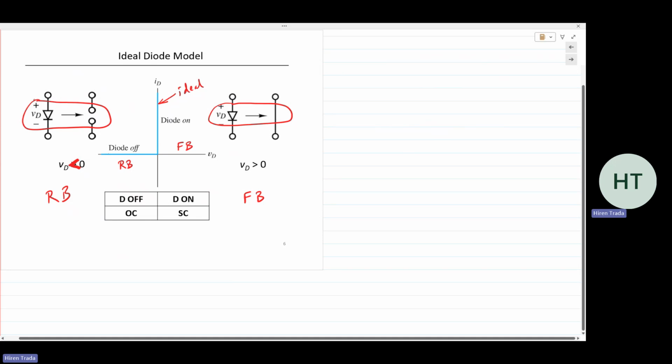In the lab, in lab 1 and even in lab 2, when we use the diodes, if we wish to analyze, we could say that when the voltage goes positive, the diode turns on, and the capacitor starts charging. When the voltage goes negative, the diode is reverse biased, replaced by an open circuit, and the capacitor has no place to discharge, so it holds the value constant. Then in the peak detector, it charges to a level of the negative voltage, depending on the connection. When it charges, it's going to hold the voltage across it constant. When it's again forward biased, the diode is now a short circuit, and the capacitor can discharge through the resistor.